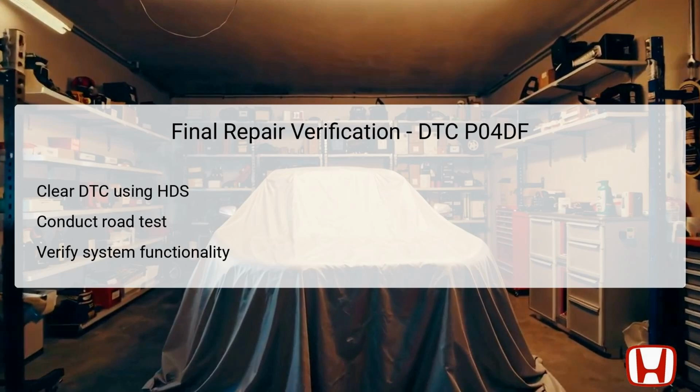After addressing the identified issues with either the EVAP canister purge valve or the vent shut valve, the next step is to verify that the repairs have resolved the DTC P04DF. Start by using the HDS to clear the stored DTC from the vehicle's memory, which will allow you to initiate a fresh evaluation of the system.